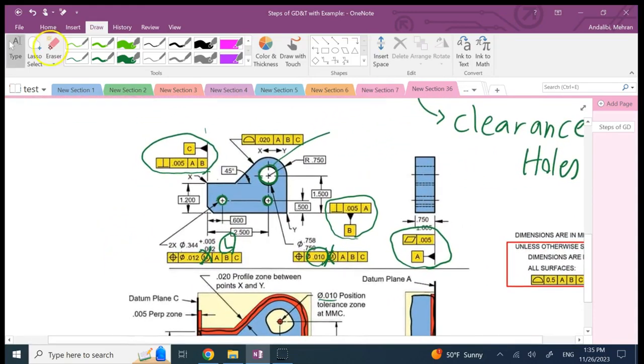Well, a simple typical thing for it is here, to get that number, we look at what? We look at the smallest size that the hole can have, in this case 0.75, right? And then we look at the size of the pin that needs to go inside this hole. And for that, okay, we look at the maximum diameter of that. So let's say in this case, this is like 0.74 and maybe 0.72, something like that.